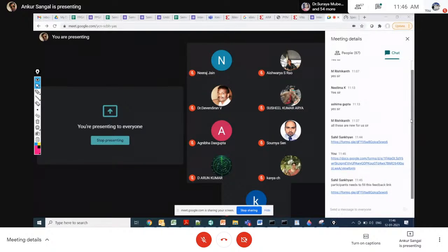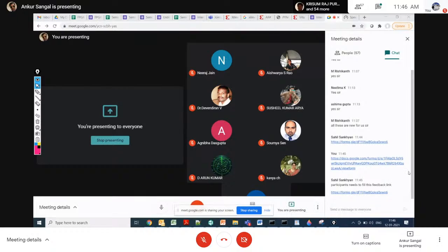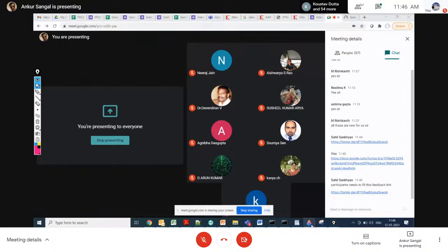So if you are talking about the new version, its size is more than 90 GB if you install it on your machine. It will take a little bit of time, because you need a minimum of 32 GB RAM for your machine if you want to work on the upgraded Vivado version.